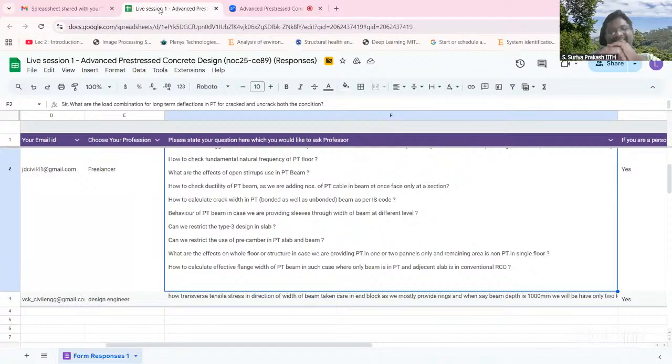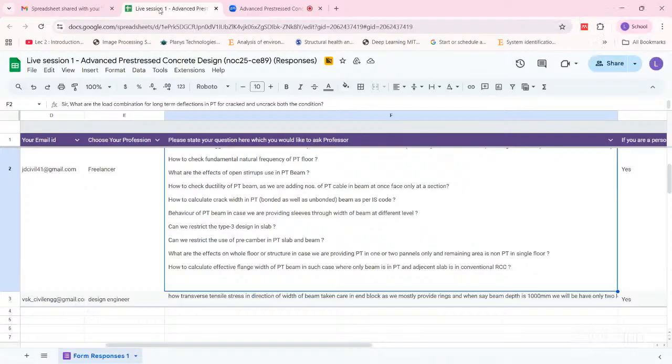Yeah, that's true. And it's very, very common. Typically, the general thumb rule is you should know the bending moment profile that you have and put the holes in locations where the bending moments are less. That is what we need to do. But I have seen, in the very worst case, people have drilled a hole just at the midspan location. You have to be very, very careful.